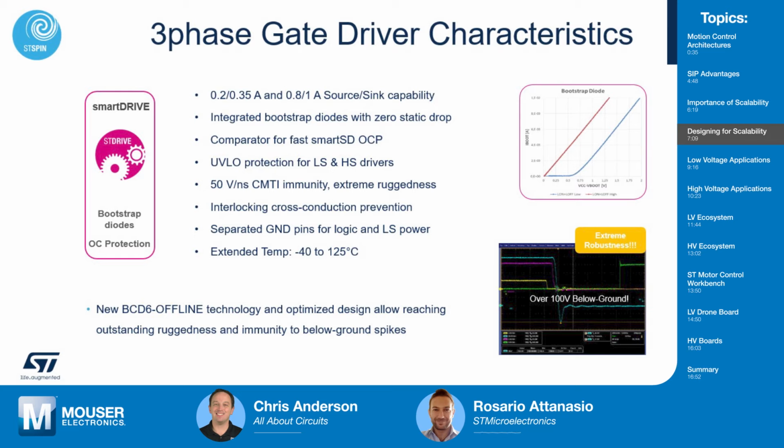And if I look at the three-phase gate drivers in particular, the characteristics that they should have, probably the list here is even longer. I would start from the gate current capability, because for a product that needs to be scaled up or down, it is very important to adapt the gate driver current capability to the type of device that I'm using, and to the figure of merit of the device. And the other really important thing, especially as the power goes up and also as the voltage goes up, is the ruggedness of the gate driver.